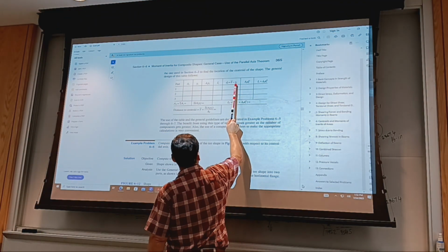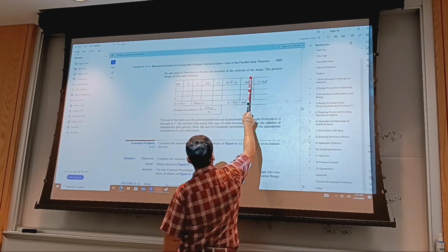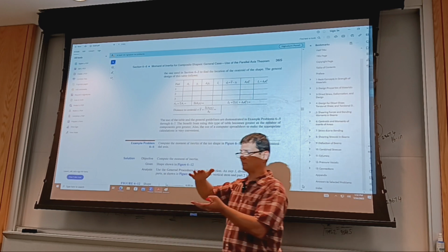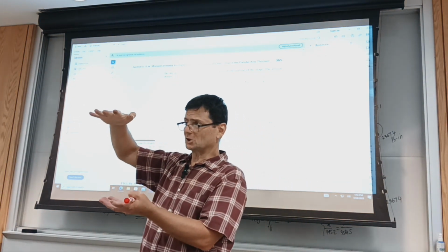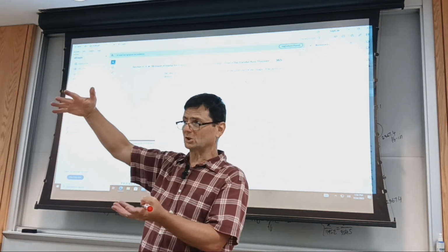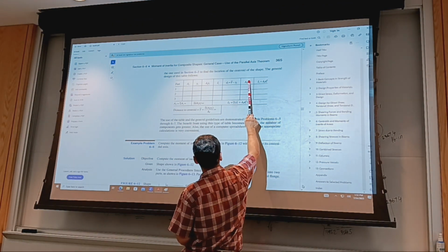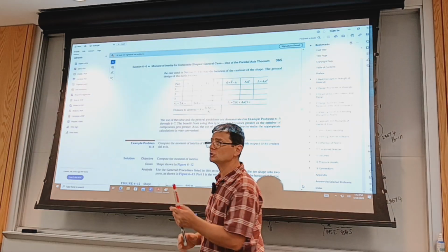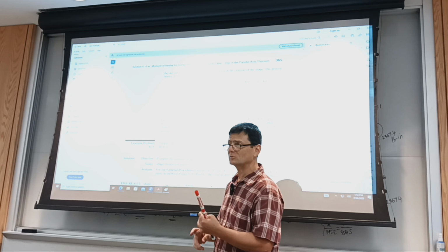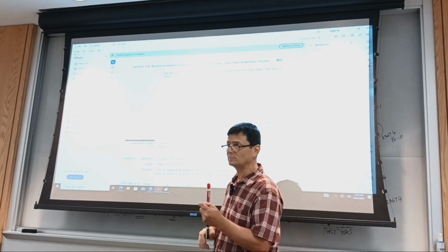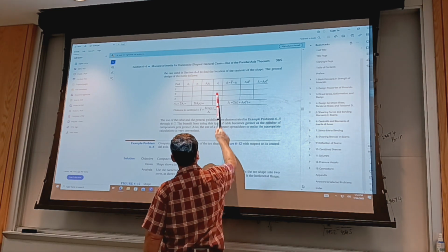And then I have, in anticipation for what is called the parallel axis theorem, because if the axis about which you evaluate the area moment of inertia is not centroidal, the moment of inertia is going to increase. The distance is squared here. Again, the parallel axis theorem, I'm sure you've heard of it. Likewise in dynamics, when working with mass moment of inertia, you use the parallel axis theorem. Okay, so these are centroidal values.